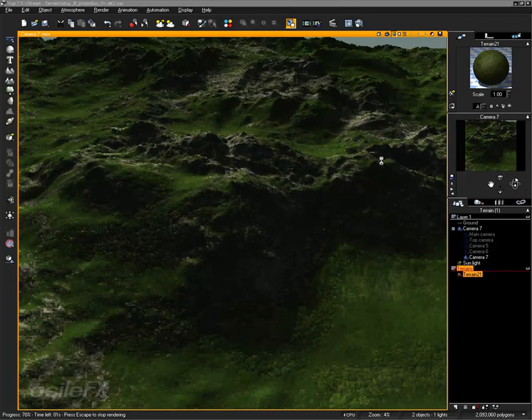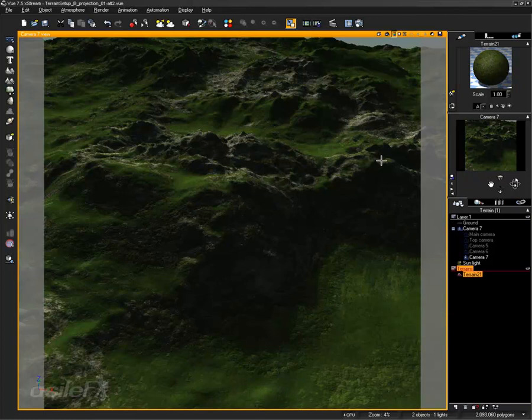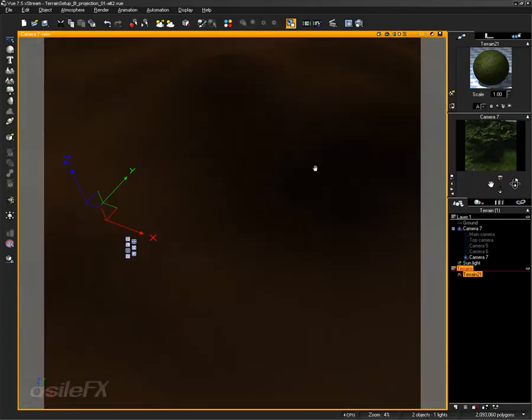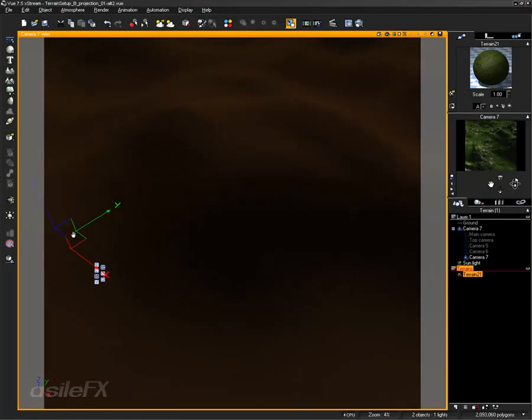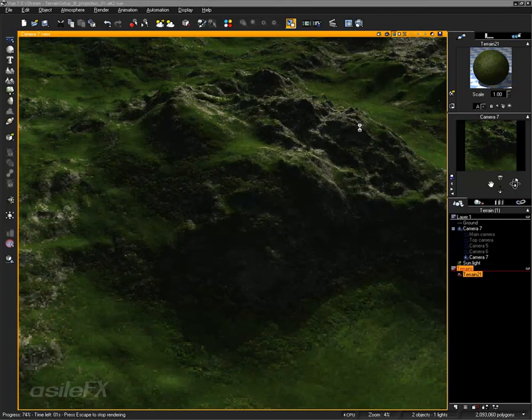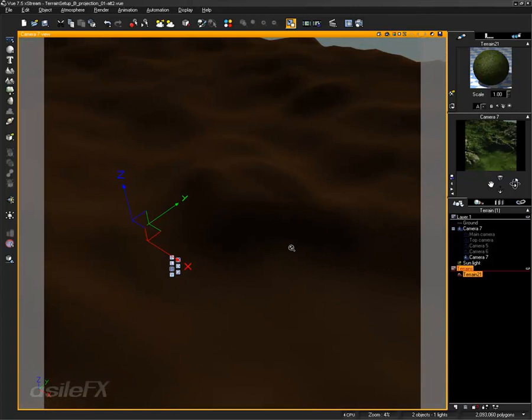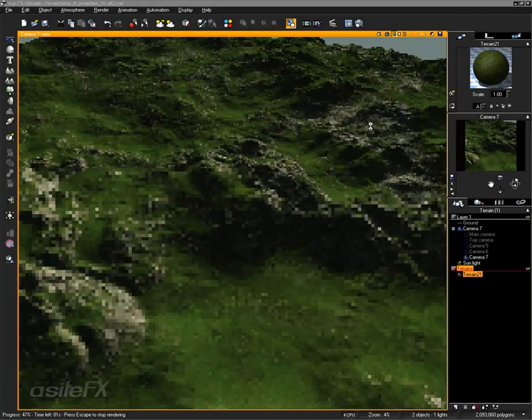And if you're using a map that already has shadows, you want to use the ignore indirect lighting, ignore atmosphere, and just use the render from before, so then you don't have to worry about the shadows in the scene, anything like that. That works great for terrain animation. You could render out a terrain pass that way very quickly, and then create another pass with the ecosystem and separate it.